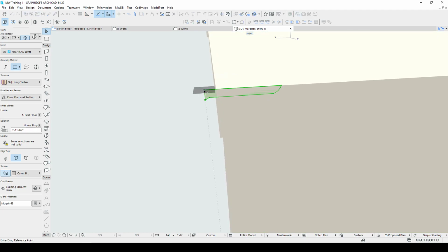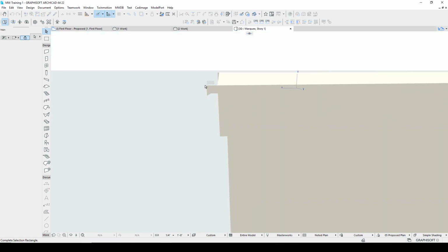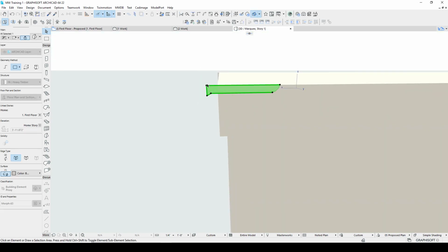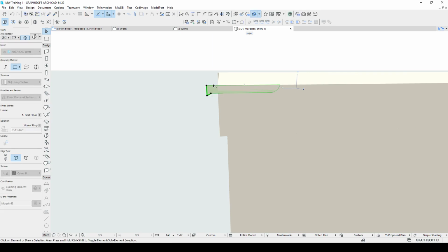And I'm going to use a shift control, which allows me to convert to the white arrow, and I'm going to hit F5. So when I do the right arrow, I go from left to right, it just selects these, and I can slide those over because I do want those to be tangent. And we'll over just a little bit as well.